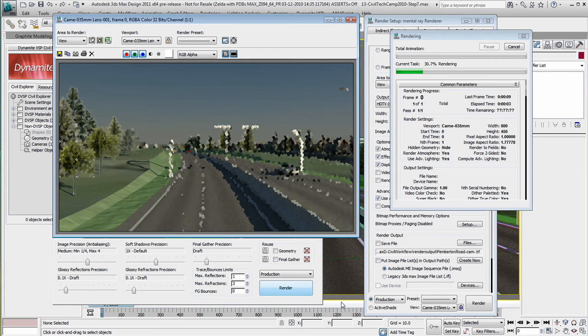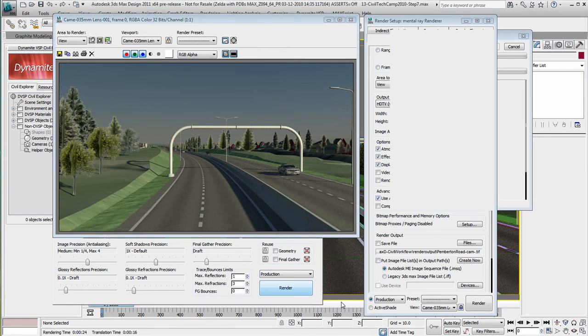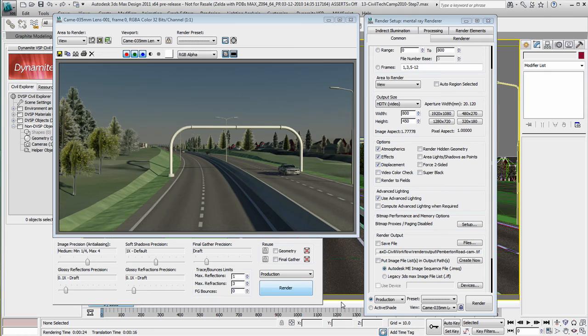When the final gather points are not locked on the geometry, they slide along the surface as the camera moves, introducing rendering glitches that look like dark moving splotches. To handle moving objects, 1 final gather map file per frame is processed in a first pass. When the beauty pass is rendered, final gather points are interpolated across multiple frames to smooth out the solution. This is what we refer to as the frame interpolation for final gather maps.